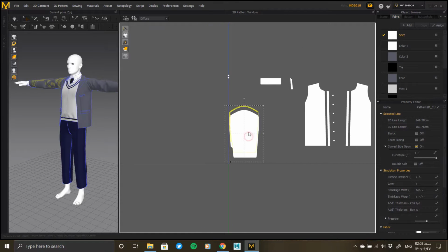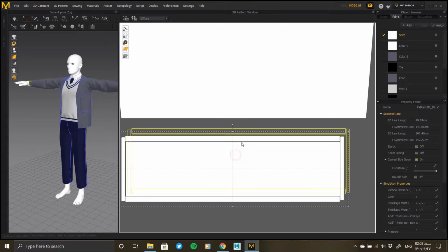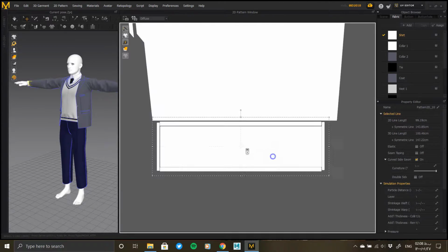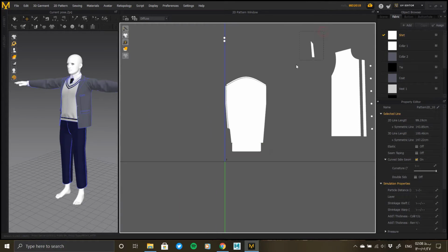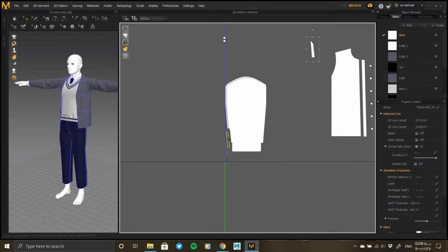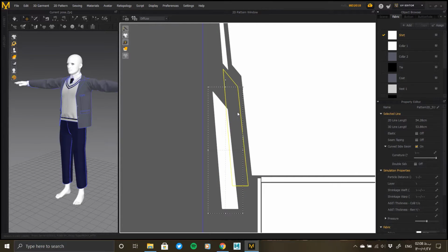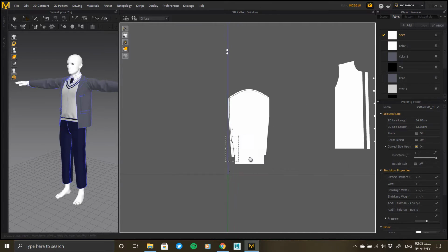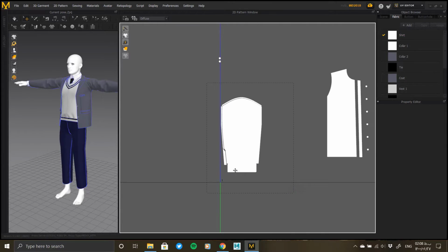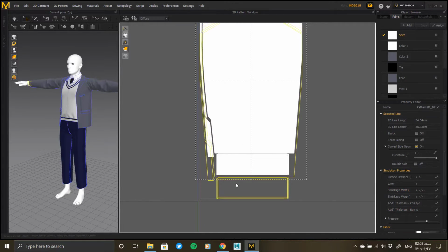The correct topology for other software is quadrilateral, and for the model to be standard, it is better to make the model topology quadrilateral. In the first case, you can select the model and select the quadrangulate option, in the 3D Garment section, in the Edit and Context menu. This command allows the irregular topology to become quadrilateral.